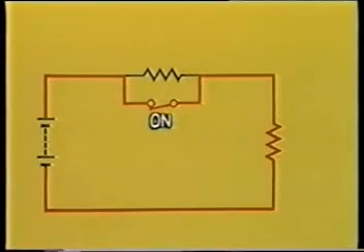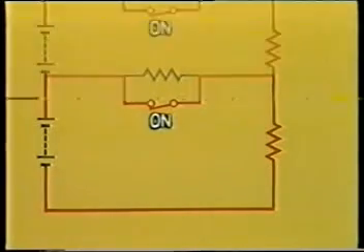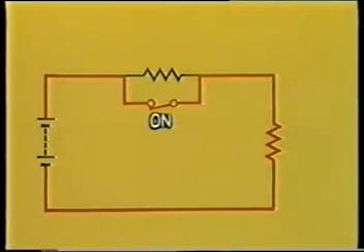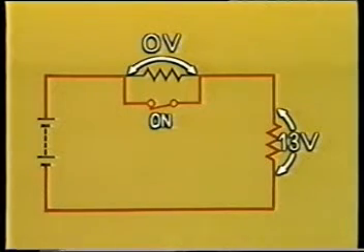When the switch is turned on, current flows as shown in the diagram. Since current flows entirely to the switch, no current runs to the lamp at the top of the circuit, and no voltage appears there. Therefore, the battery's voltage is applied entirely to the other lamp on the right side. The circuit's resistance becomes lower, and current increases in this condition.